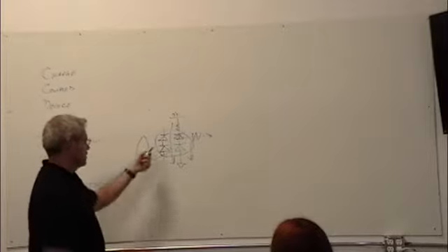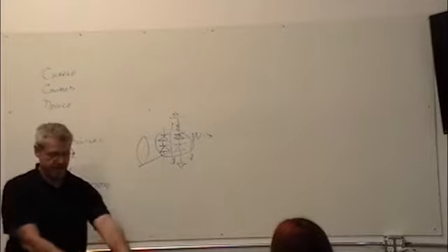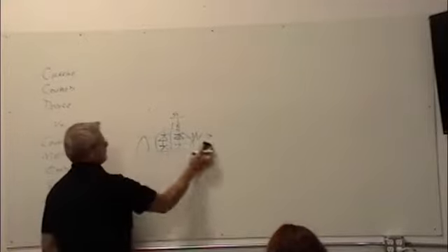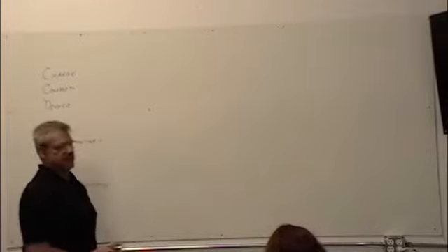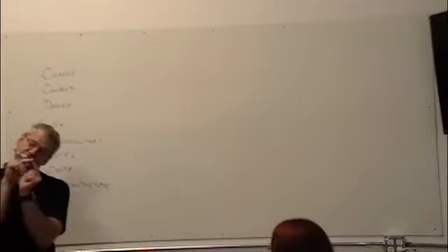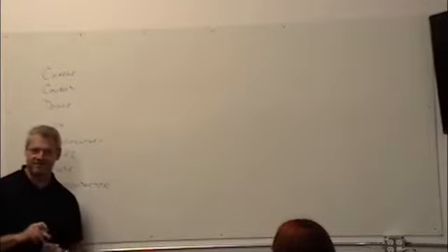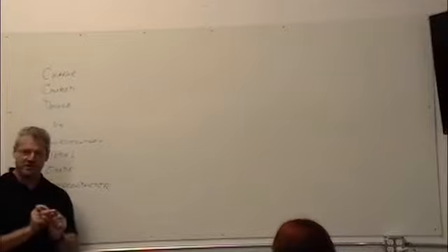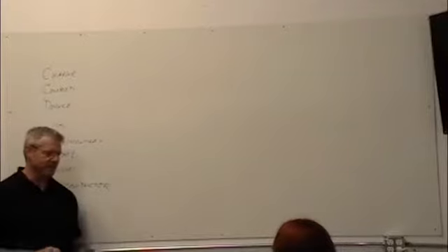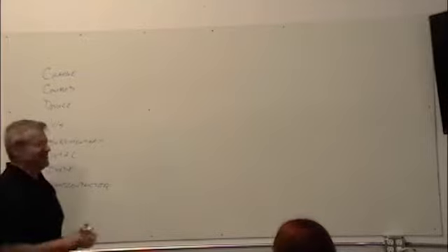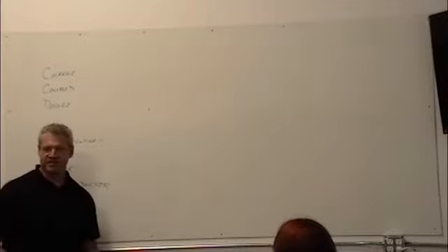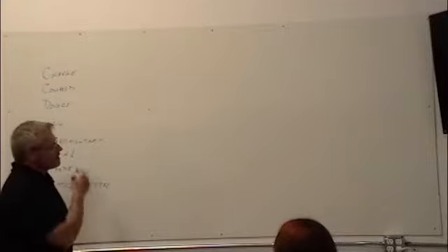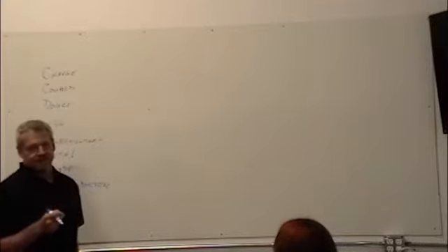So the very first imagers were actually just diodes, biased up. And they're like, wow, this is neat. And I've seen some things where they've done, I don't know, maybe 10 by 10 little diodes, way back in the days of Fairchild Semiconductor being relatively new. But it wasn't useful. I mean, it is, but the amount of effort you had to put into it to get it working made this one little thing really, really expensive. 4x4 got a lot of traction.